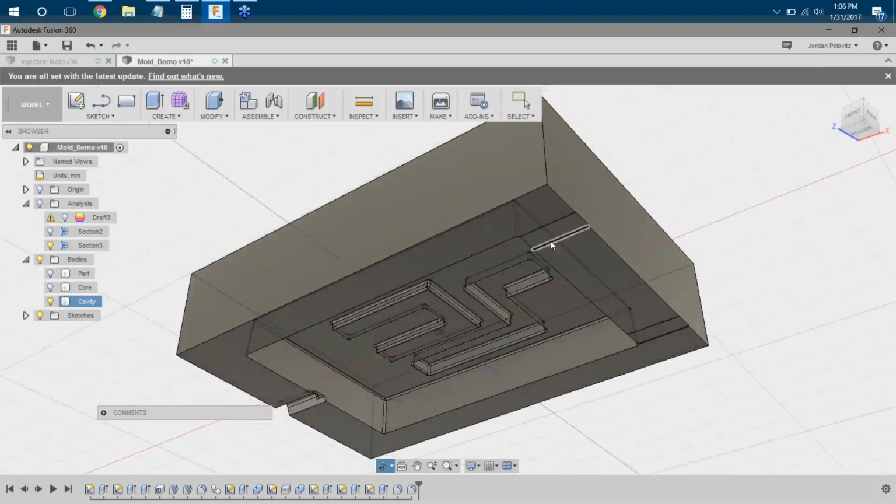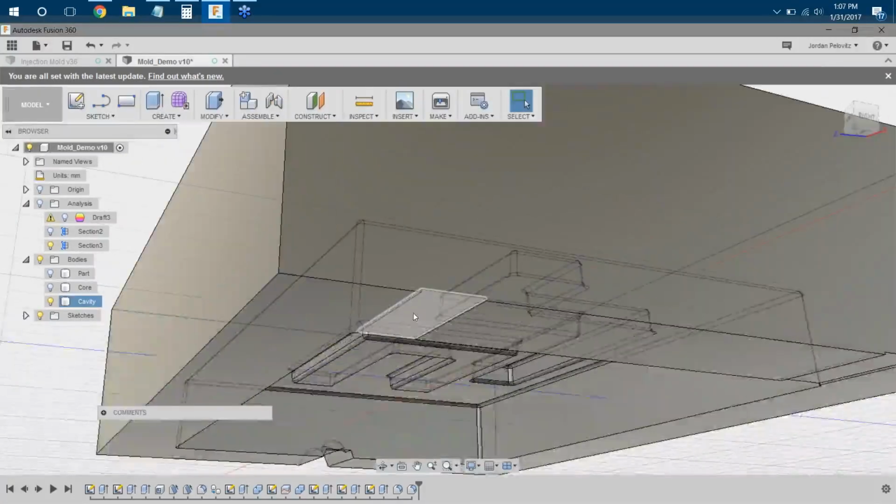With the runners, with air vents, you also want to only put them on one side. You don't really need to put them on both sides. So sprues and gates and stuff like that go on both sides. Runners really only stick to one side. And you can think of them kind of like flash on purpose. You want them just tall enough to let air out, but not tall enough to let a lot of plastic out.